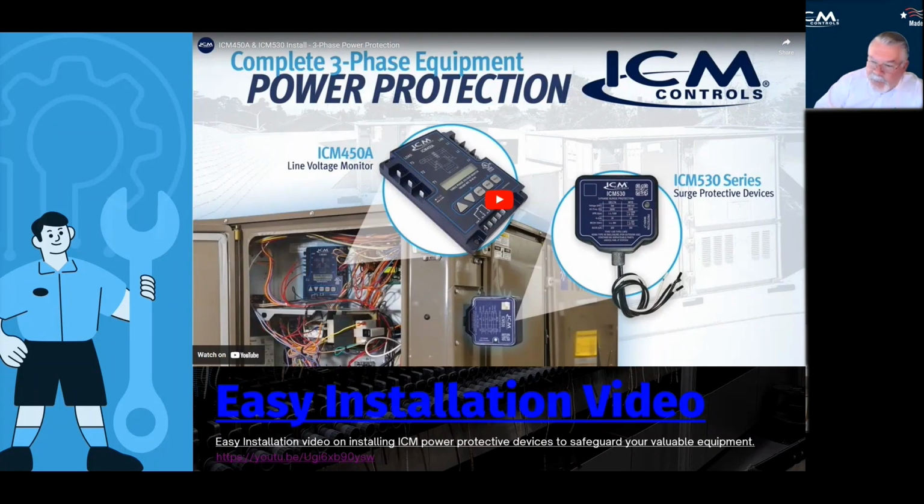So the good thing about the line monitor is it does protect you from over and under voltage. Brownouts are equally dangerous to equipment, but the spikes, the line monitor can't really do much about that. So the surge protection device is very, very critical, and we're going to spend a little bit of time talking about that here going forward. But nice installation video there on how to install those.